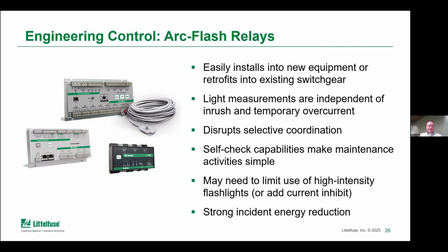One note is that there may need to be some limitation of use of high-intensity flashlights, or utilize a current inhibit signal that looks at both current and light to pass the trip signal forward. But the bottom line is that arc flash relays do provide solid incident energy reduction, and they're something that can be quite easily applied both for new equipment and retrofit.